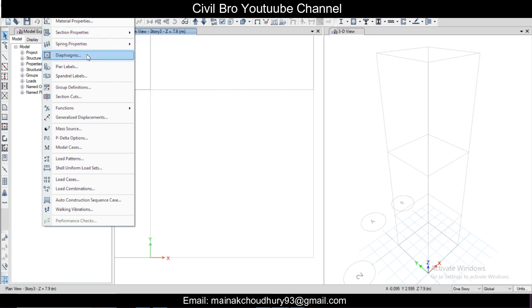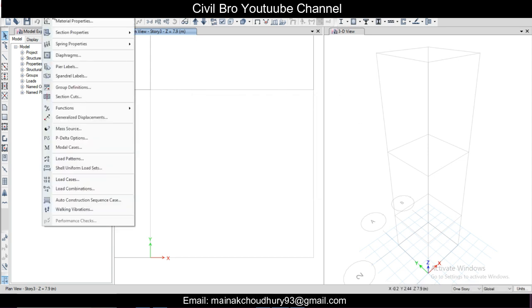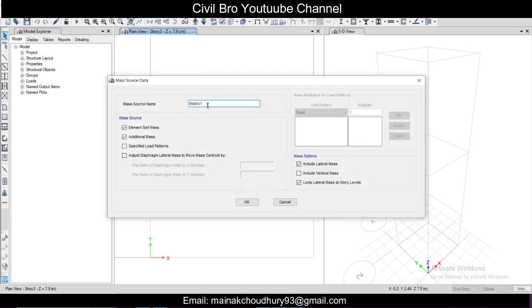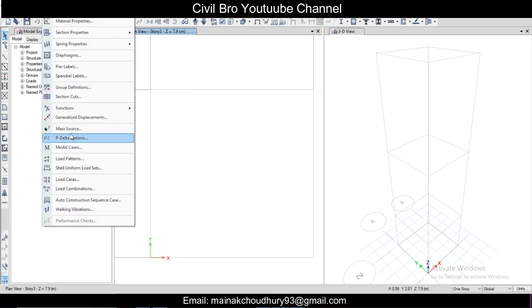Then we will define our diaphragms. We have 2 floors, so add another diaphragm, rigid. One is already there, so 2 diaphragms for 2 floors, it's okay. And then we will define our mass source. We'll modify this particular mass source, and before defining the mass source I think we need to define the loads, so it will be better.